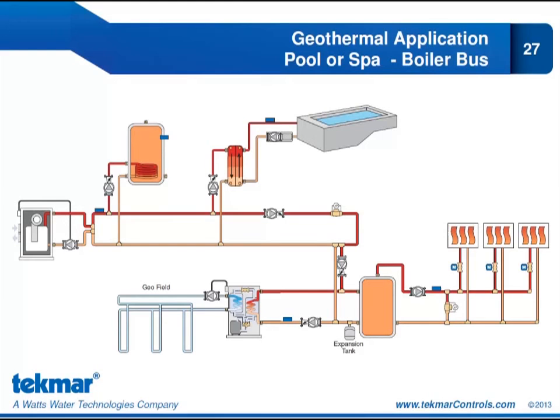So in this application, I have a water-to-water heat pump that is maintaining my buffer tank at a target temperature strictly for my radiant zones. And my boiler is going to be providing the heat for domestic hot water and for the pool or spa. Now this boiler can also boost my buffer tank temperature if for some reason the heat pump can't keep up. Now let's look at the electrical diagram on the following slide.